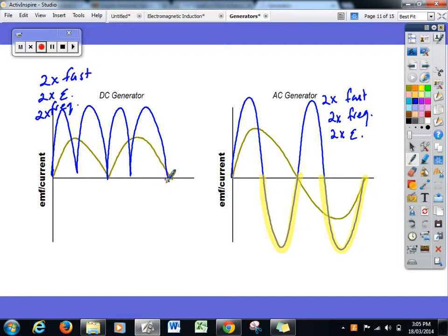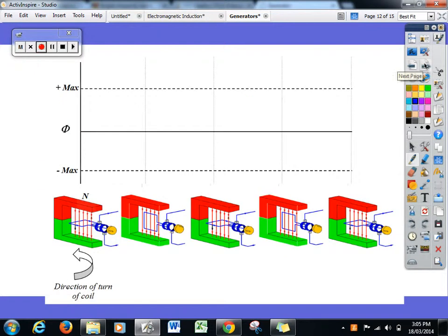So, are those 2 humps the bottom, the negative? Yes. So that one there is that one there. Oh, but then what are the 2 underneath that? So this green colour, that was a single turn. Oh, okay. So the green colour was 1 single revolution of the coil, and the blue is when I turn it twice as fast. So I get twice as many humps and twice as much electricity coming out. Okay?